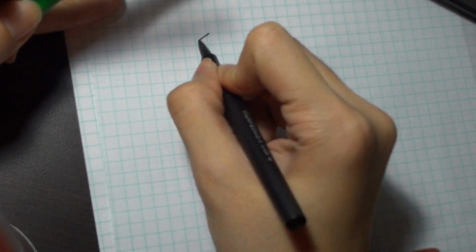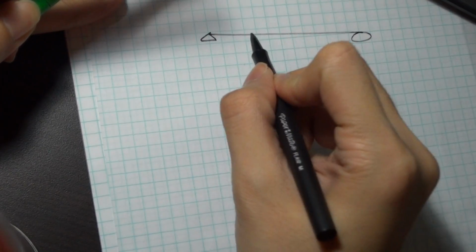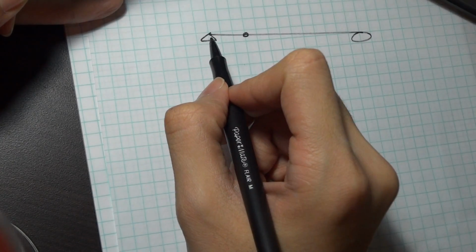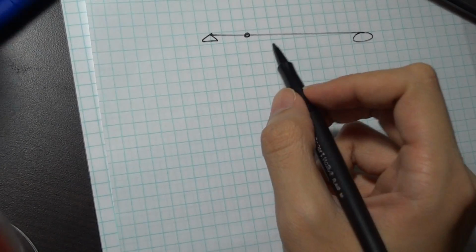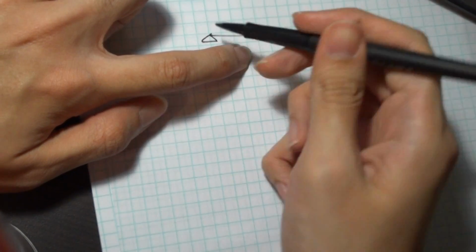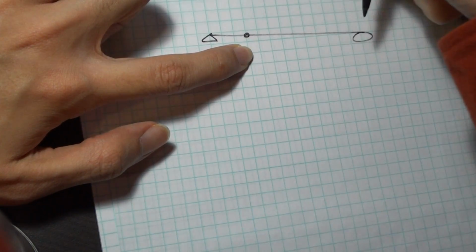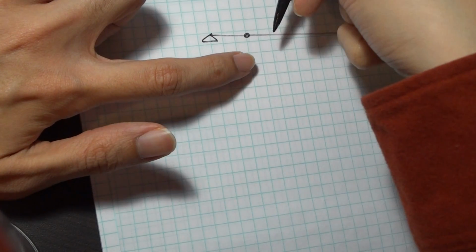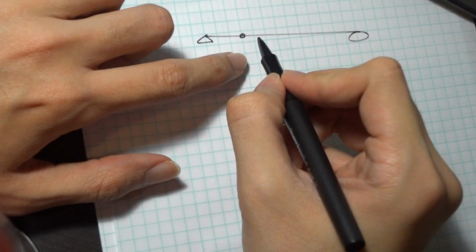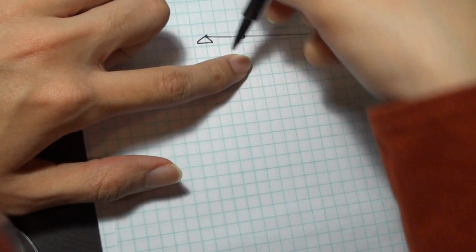So recall that for influence lines, we're looking at a single point on our graph. So let's say at this point, and I'm trying to see what happens as I move a load across this beam. For example, if I'm interested in the shear at this point, what is the shear as I have a point load move across the entire thing? Normally I have a load at a single point, and I'm interested in finding the shear at all points in the beam due to that load.